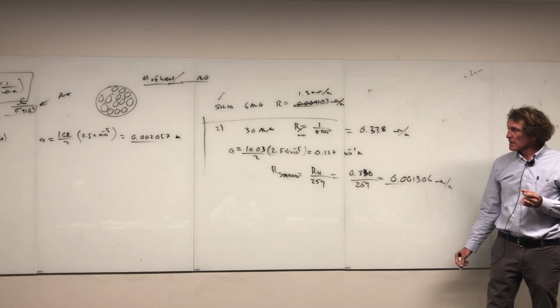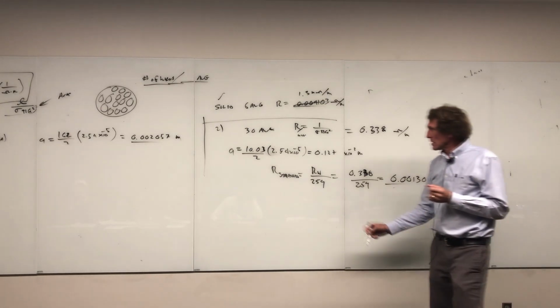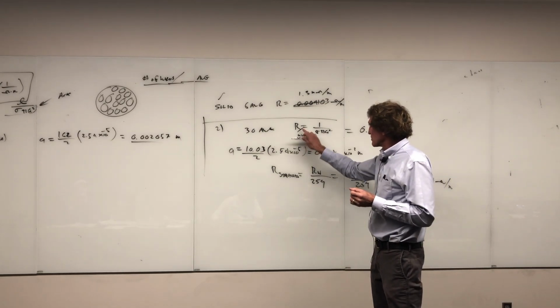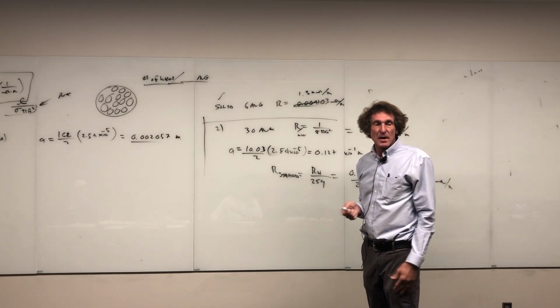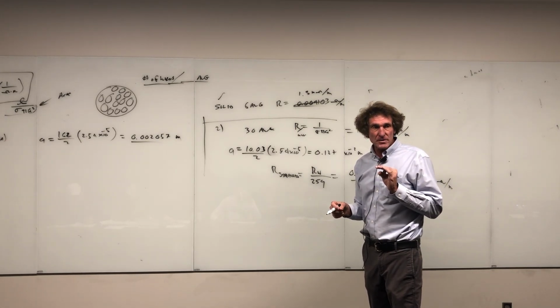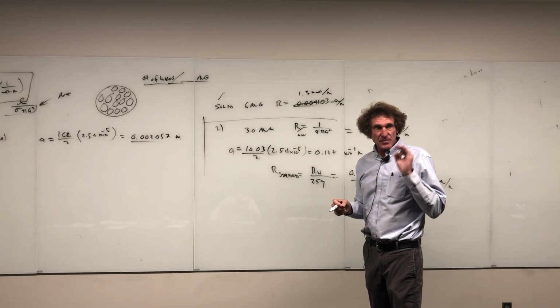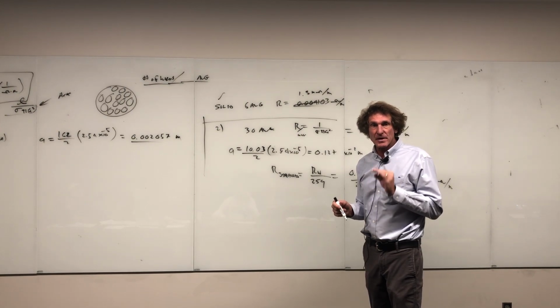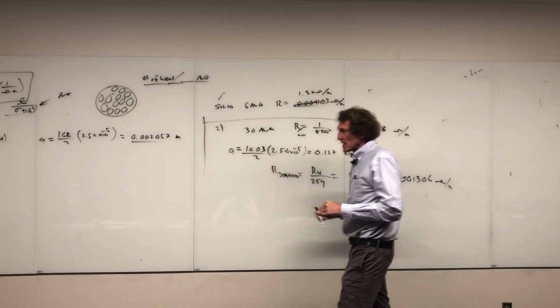What is that under the R next to your radius formula? This? Yes. I just said per wire. It's resistance per wire. But what you always do is look at the resistance per wire and divide by the number of wires with stranded wire. And you have to be really careful when you get to high frequency. Here's the real thing that happens.